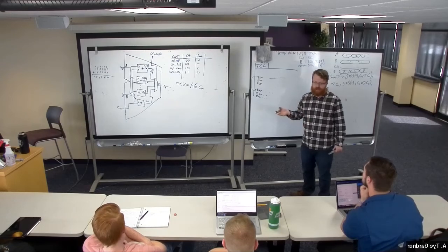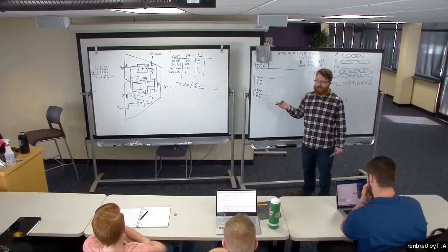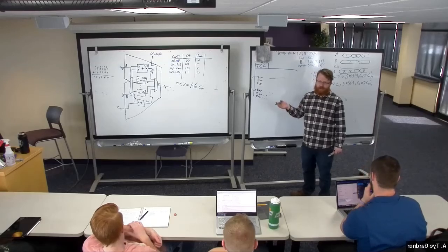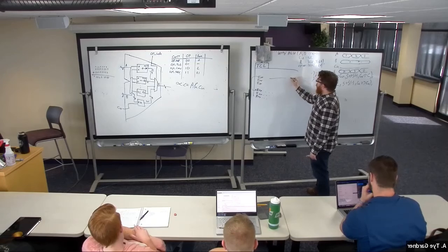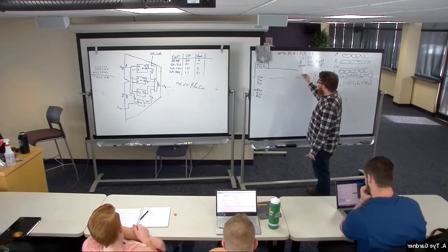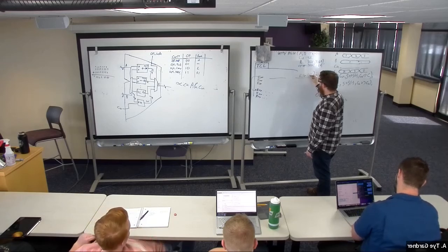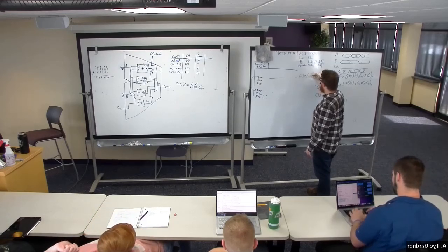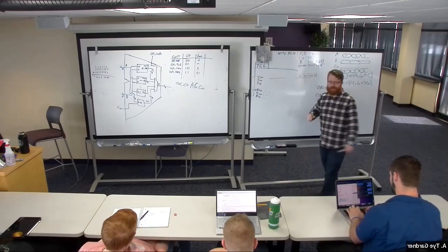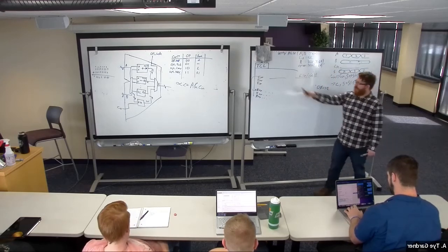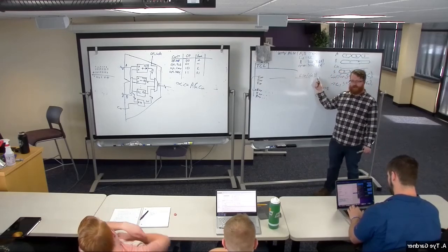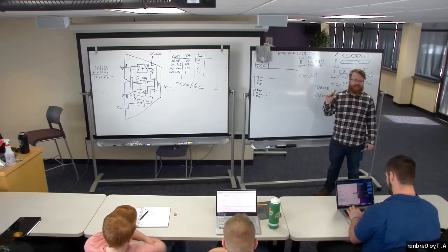It's going to be like your signal sizes don't match because you tried to plug a 3-bit vector into a 4-bit vector, or a standard logic into a standard logic vector. The types don't match. Whatever the error happens to be, later it's actually going to tell you the file and the line number.